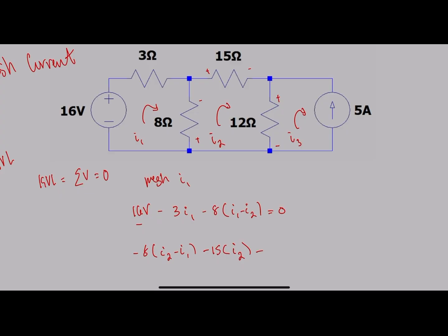And then finally, we'll have this mesh here. Now I3 is kind of like the dummy voltage, so to speak, of the last example, since we have an independent current source here, we already know this is going to be 5 amps. And since we defined it in the opposite direction, we know I3 equals negative 5 amps. But that is kind of redundant.